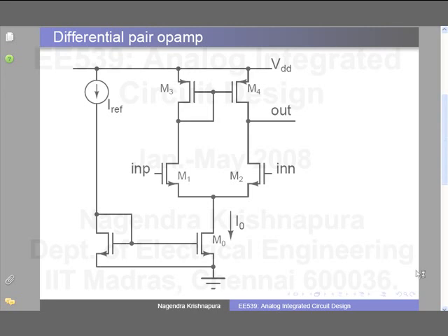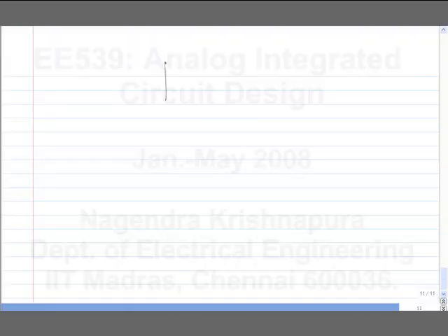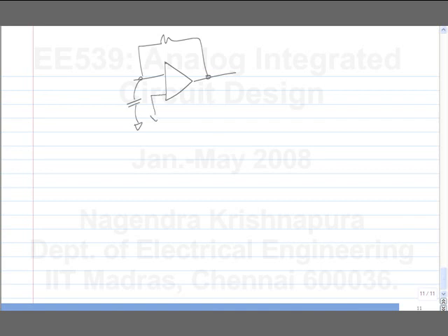Why is that important? Have you seen a case where the input capacitance of an op-amp is important? We have seen it several times. If you have an amplifier with a resistance and feedback, and you have something like this, what does this do? Ringing. It introduces an additional pole in the feedback path, and you can have ringing and instability. So that's why that's also important.